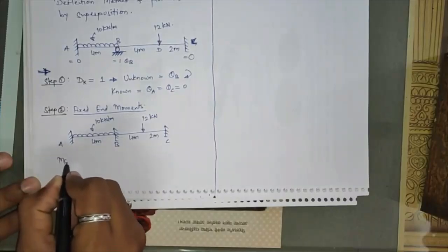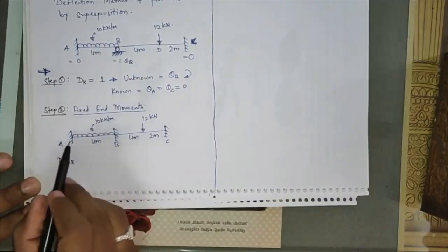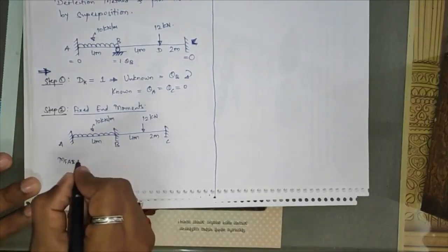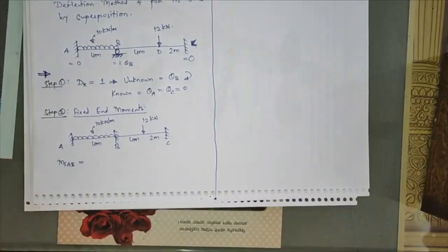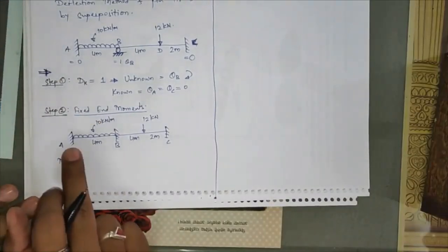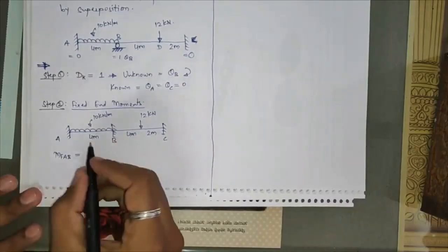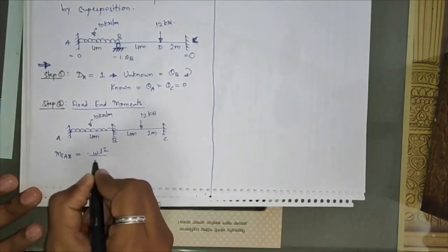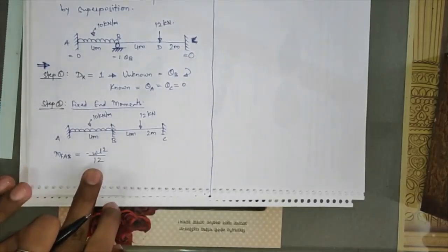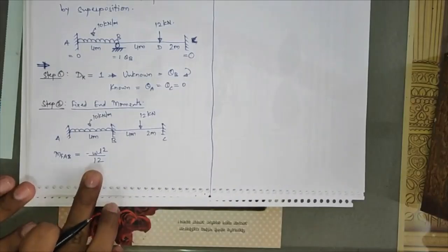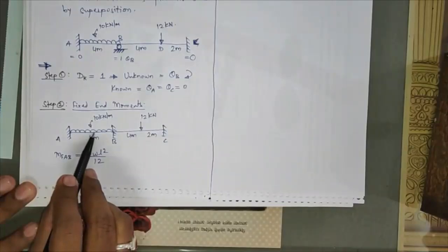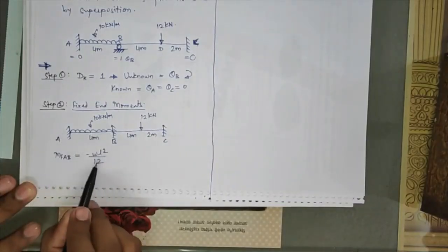First, the fixed end moment at your first joint, that is AB. So the fixed end moment at A will be your MF AB, equal to what is given for span AB. It is completely loaded with the UDL. So your fixed end moment comes equal to minus WL square divided by 12. How these values come, we have seen a table for that. Okay, in SA1 we have seen the table. If UDL is present throughout the span, your fixed end moment value comes equal to WL square by 12.